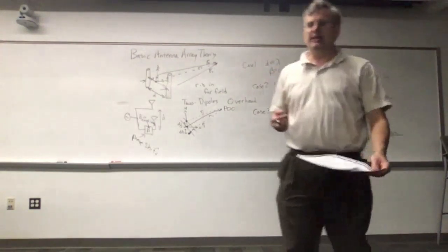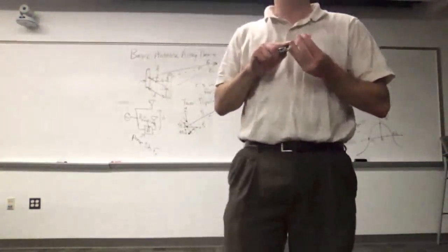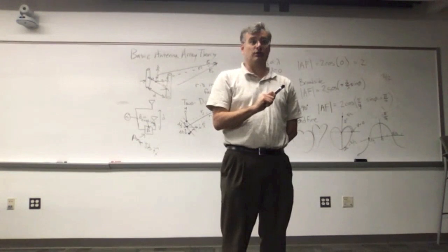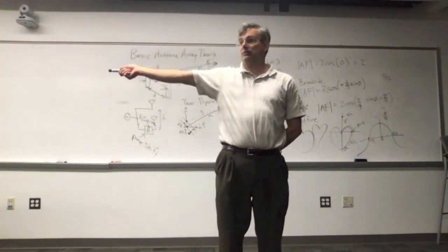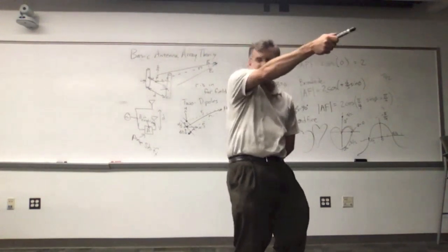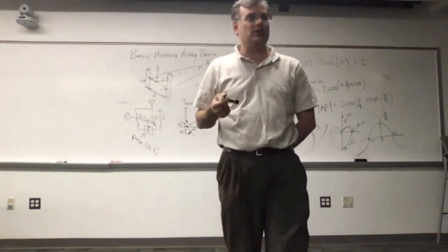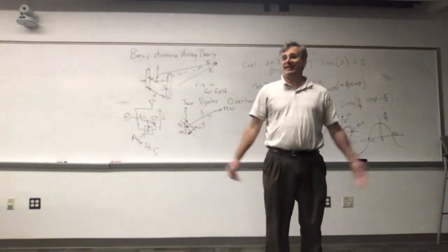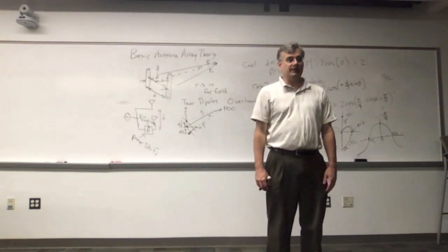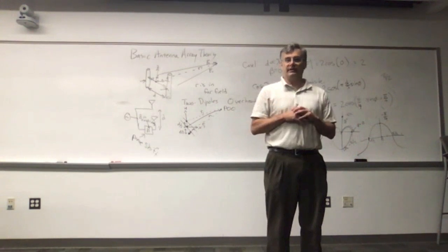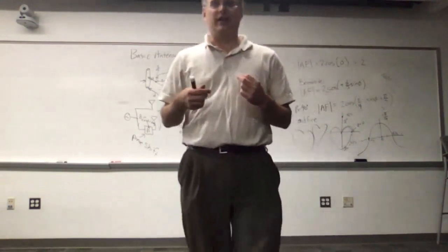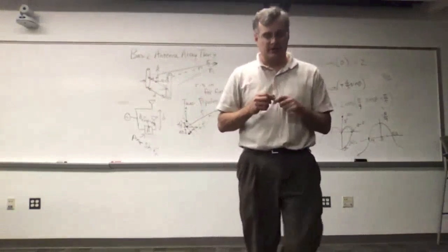So now we actually see the beginnings of the idea of a dynamic array, an antenna array that can be electronically adjusted and steered anywhere in the environment. Here, that's end fire, which is 0 degrees. Over here, 90 degrees. Positive 90 degrees over here. If I want to get something off axis and put my peak gain in that direction, then I just need to dial in something between those values using this mathematical transformation, the array factor. And then I can do that with arrays of all sizes. The devil's in the details, though, because you've got to have phases that are properly connected. You've got to have phase networks that are low loss, which is really hard to do, especially at higher frequencies. You have to know how to map the desired phase to what you're trying to get on the outcome.